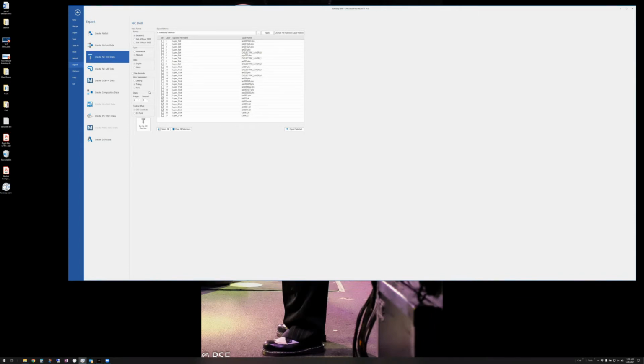The uniqueness of those two formats is it does not require component information. It supports it, but it doesn't require it. If, for whatever reason, I was trying to create a CAD database, and maybe that's GenCAD, the two grayed out ones, or PADS ASCII, those formats require intelligent formats, require components to be present. So you have to do a lot of work in order to export those formats. Basically, you have to reverse engineer the design. So you're probably not going to do that.